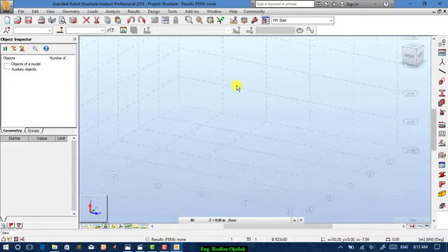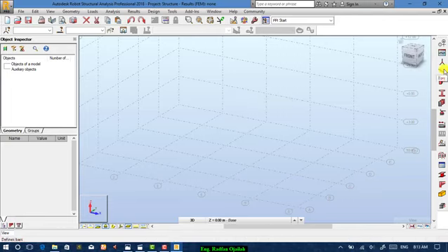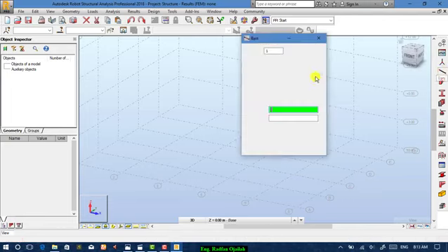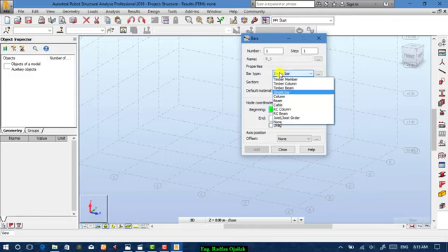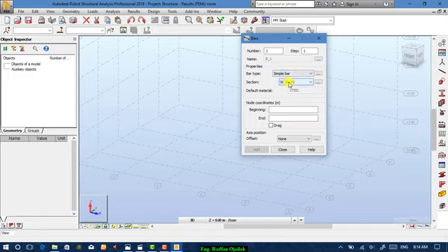Now the most important thing is the drawing process. To start drawing columns and beams, you don't have to select beam and start drawing beams, or select the column and start drawing columns. No, all you have to do is select these bars, and you do not have to specify that you want column or beam, just simple bar, but different sections for columns or beams.